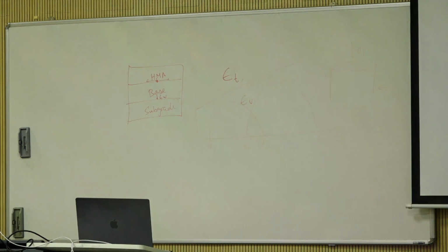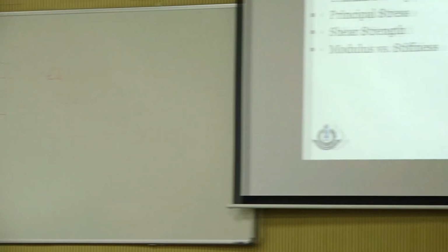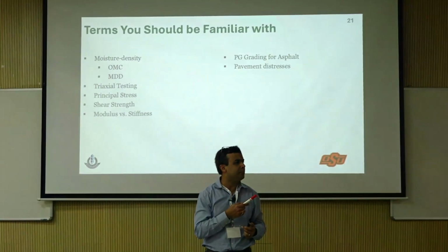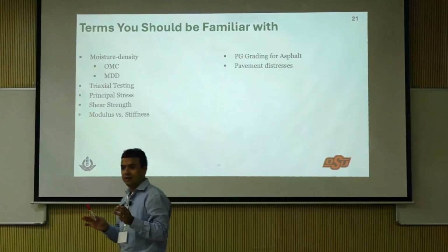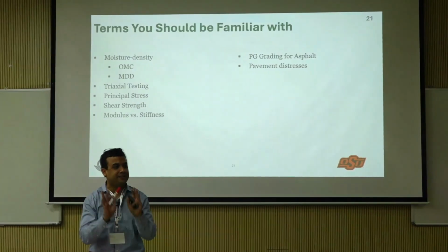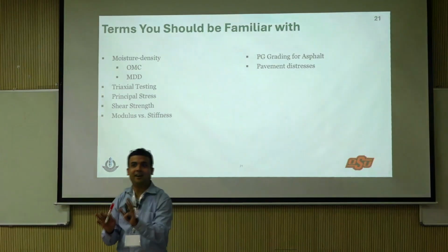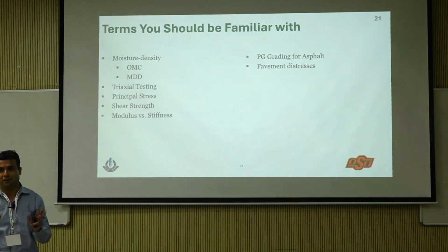How many of you have run IIT PAVE? Is IIT PAVE finite element or layered elastic? Layered elastic. So have you run IIT PAVE? I can guarantee that if you run it, you will see tensile strain in the base layer. That is a manifestation of layered elastic analysis theory.